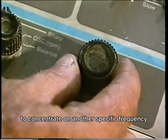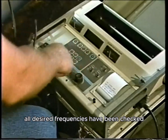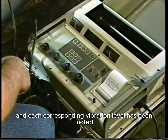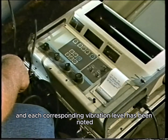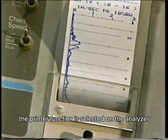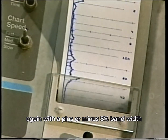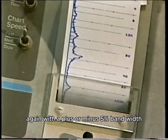Once the amplitude of the vibration is determined, the analyzer can be readjusted as necessary to concentrate on another specific frequency. This process continues until all desired frequencies have been checked and each corresponding vibration level has been noted. To get a printed chart of the reading, the printer function is selected on the analyzer. The analyzer then prints the chart, again with a plus or minus 5% bandwidth.